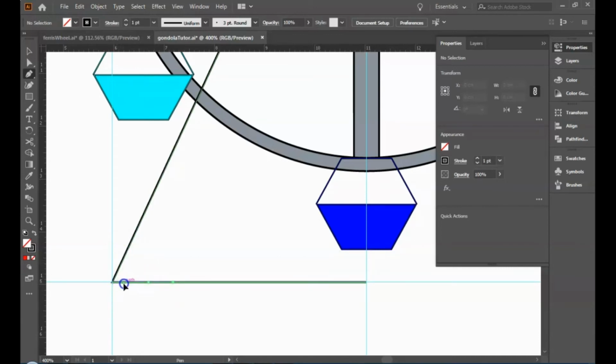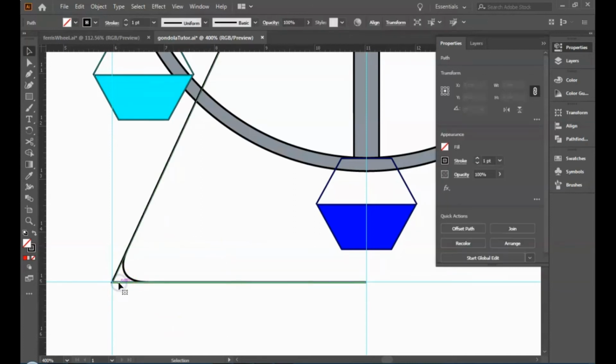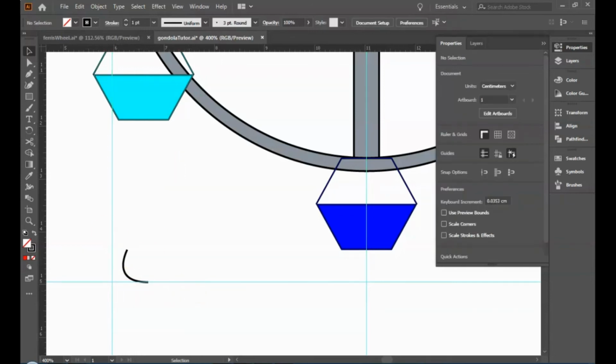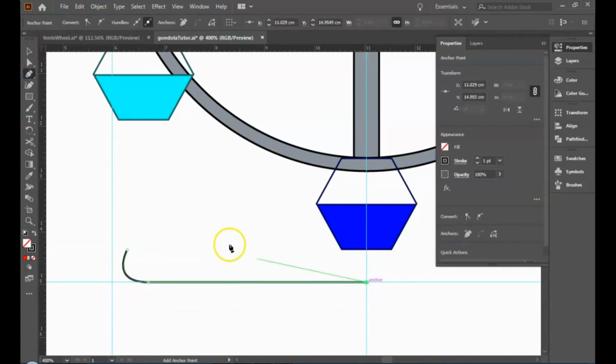Now I want to start here and make a handle. I drag, because I want this to be a curved path. Stop there. You can see it's curved already, so I'm going to pick any intersection point. Make sure that it's on that path. Just let go. Now that I have it, I can either snip this off using the scissor, or I can delete this and just draw a new one. Up to you. I find it easier to just draw a new one.